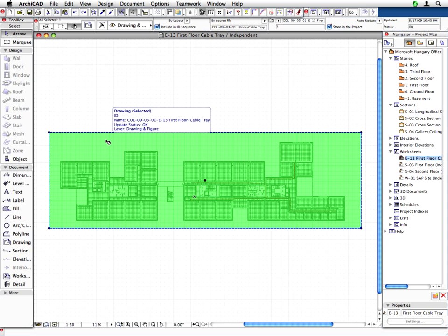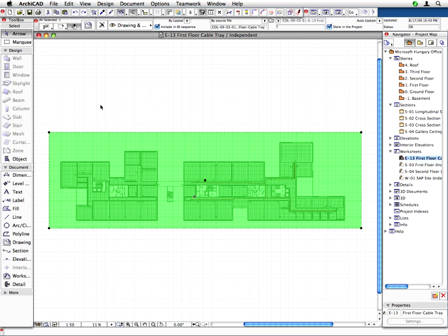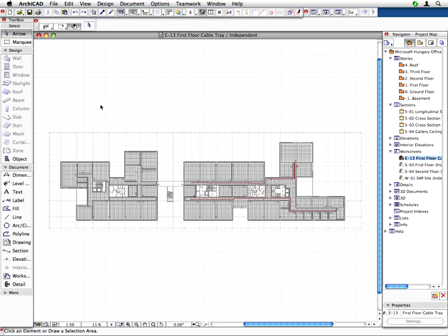One of the most important purposes for placing external files this way is to guard our original attribute set and avoid attribute pollution. Attribute pollution is the unnecessary increase in attributes due to the placed and xrefed DXF and DWG files. When we place a DWG file as a drawing, we do not get many unwanted layers and other attributes. When exploding a drawing, all elements of the DWG file can be transferred to a single layer, as you were able to see in the previous steps.